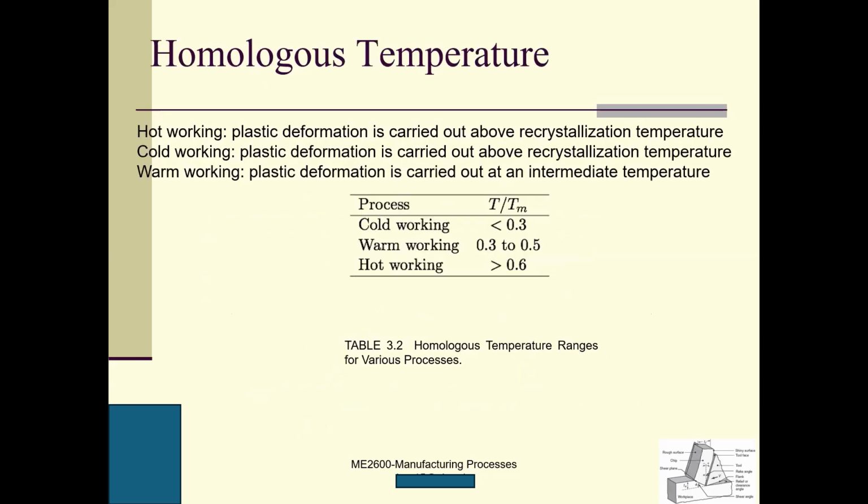And then we talk about homologous temperature. Last time I think I introduced two working conditions, one is hot, one is warm. But sometimes people introduce hot and cold, and here is the third one. You can see the demarcation line is the recrystallization temperature. So it's hot working.